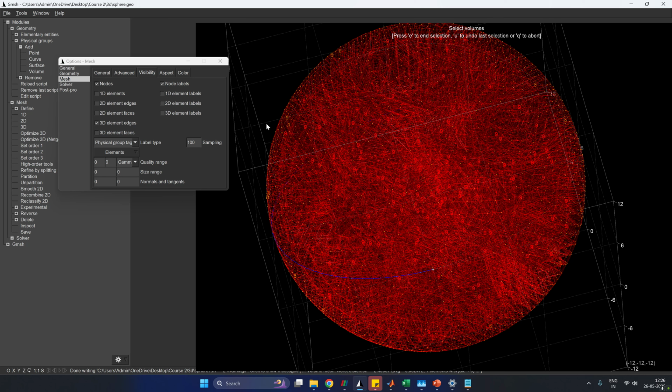In that case, you would have a Robin boundary condition at the electrode. Or if you think of a wall function, which we also discussed in turbulent flow, those are also Robin boundary conditions. You also have weak imposition of Dirichlet conditions, but I'm not showing it here because it's a bit more advanced. So that's about it.